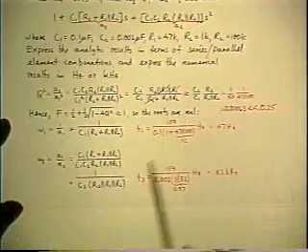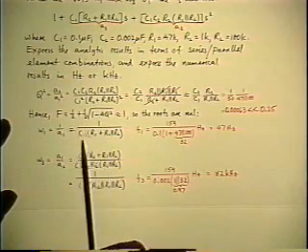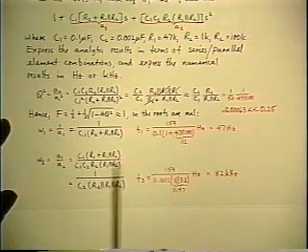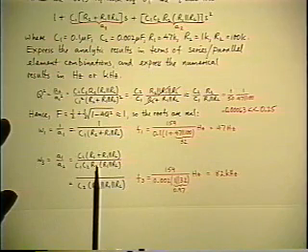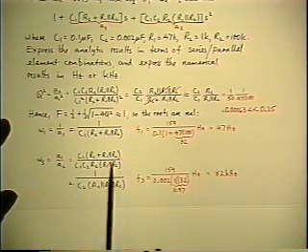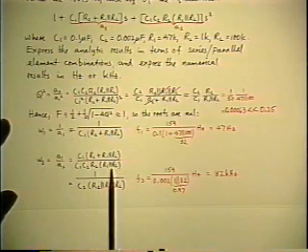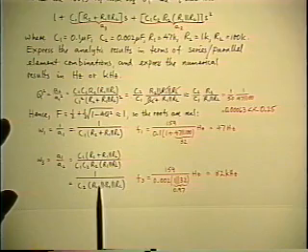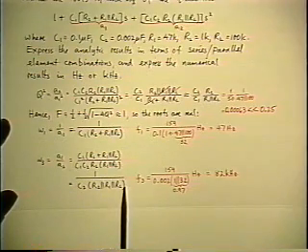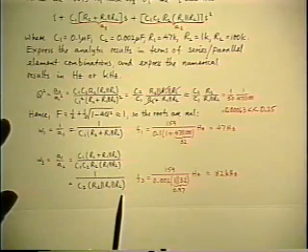And when you make that substitution, the A1 is already explicit, and it gives you directly a corner frequency. The other result is immediately reducible because the C1 cancels, and you're left with sum over product, which is 1 over parallel combination, in which one of the components is already a parallel combination.